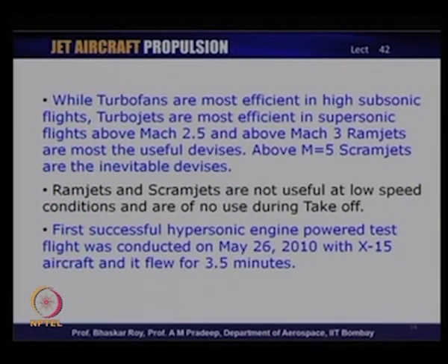When you have turbofans operating at subsonic to high subsonic to transonic speeds, they are the most efficient jet engines for powering aircraft. However, it is generally felt that once you cross about Mach 2 or 2.5, turbofans would become less and less efficient, and pure turbojets would be the more efficient device. Aircraft that fly at very high speed will also experience very high drag. So, the drag penalty for thrust creation becomes a little prohibitive with turbofans,